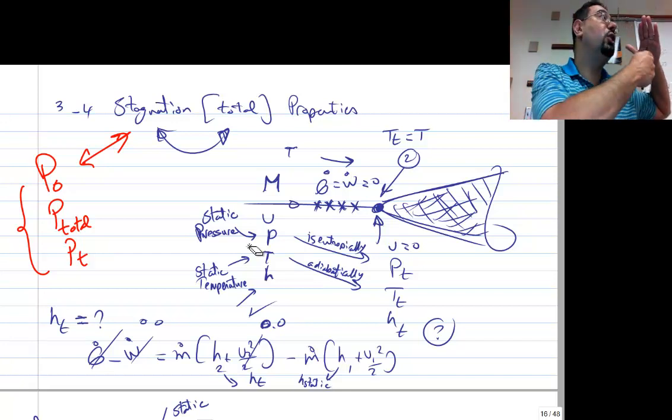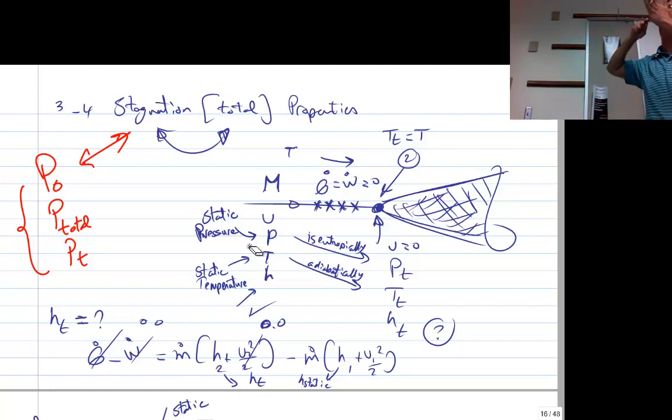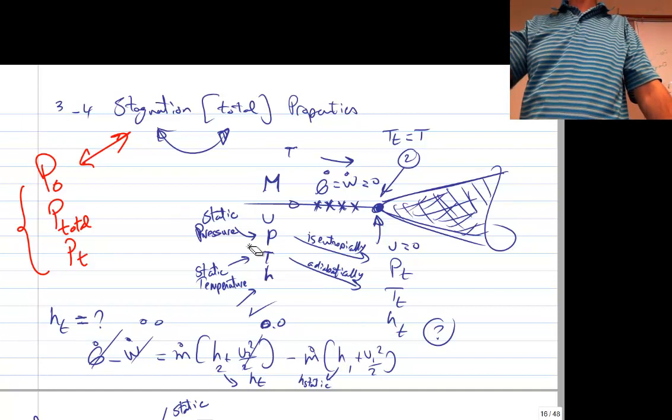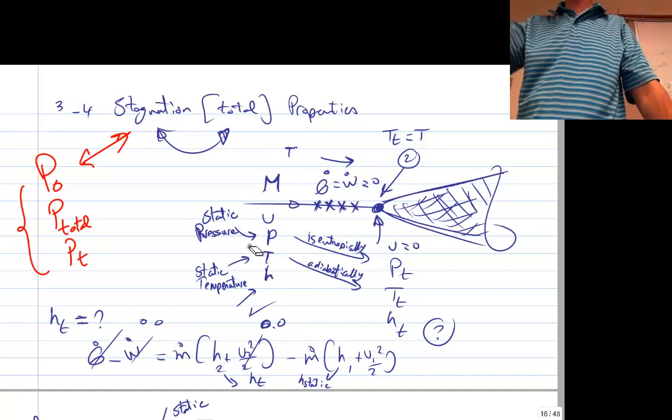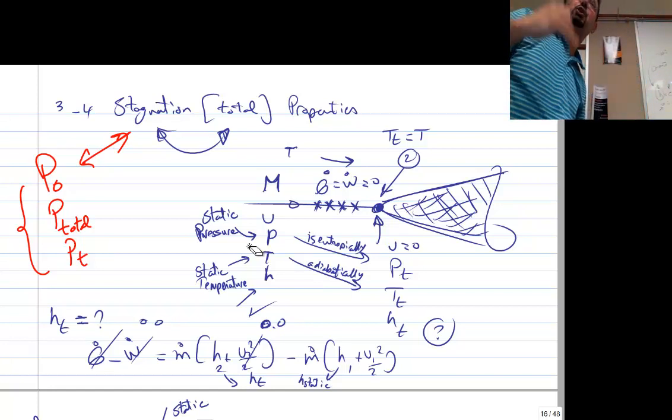They tell you that to measure it, you have to be static with respect to the air. So you take your probe, a thermometer, and you run with the air, basically. Then you will be measuring the static temperature. But if you stop the thermometer like this in the wind tunnel, the air will have to stop at the tip of the thermometer. That's the stagnation temperature. You are measuring the temperature of the non-moving air, the stagnating air. So anytime you hear static temperature, tell yourself in your head, the moving air temperature. The static pressure, that's the moving air pressure.